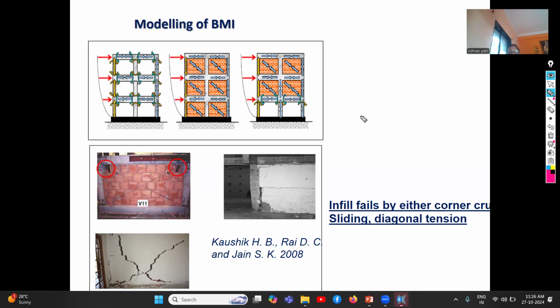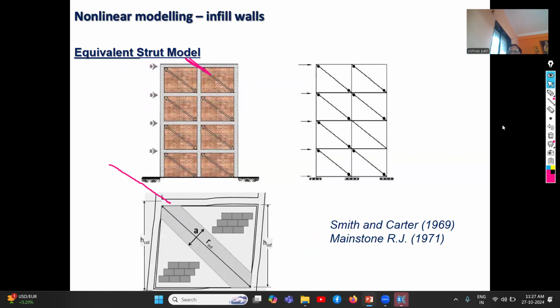It is observed how the masonry fails during an earthquake. Whenever the lateral load is there, that lateral load passes through the masonry in the diagonal direction, like this. Therefore, the diagonal portion of the masonry fails under crushing, axial loading. It gets crushed. So, an axial hinge, showing this failure, we have to assign to the masonry. So it is an axial hinge.